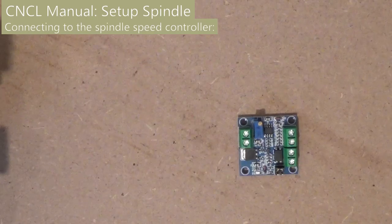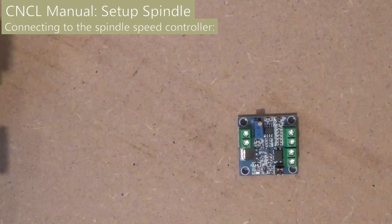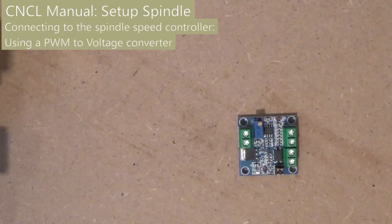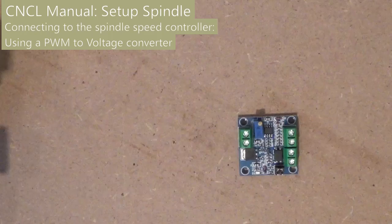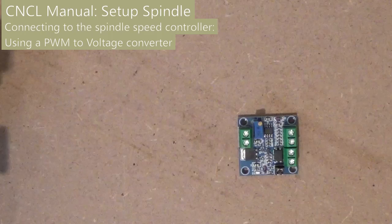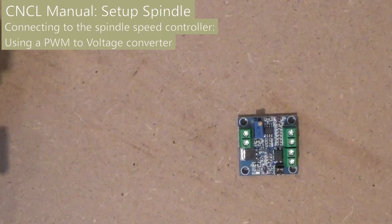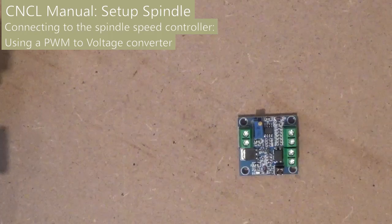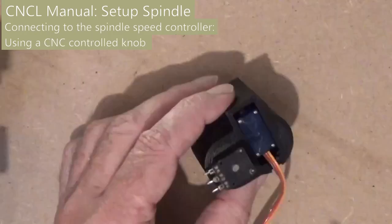Most of my controllers accept a PWM signal. My lathe, however, needs a 0 to 10 volts analog signal. I use this cheap $3 PWM to voltage converter. It will convert the PWM signal to an adjustable 0 to 10 volt analog output signal.